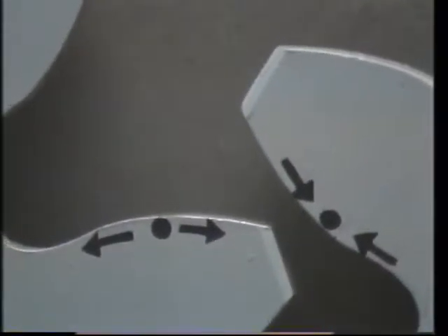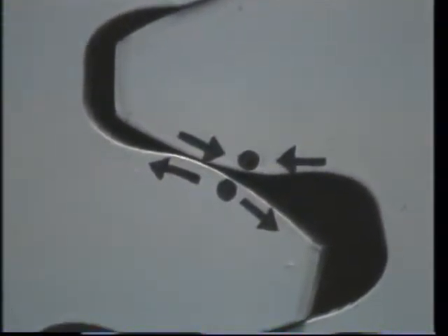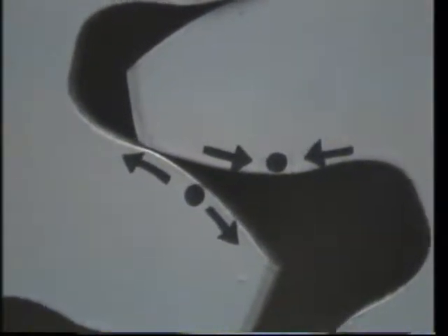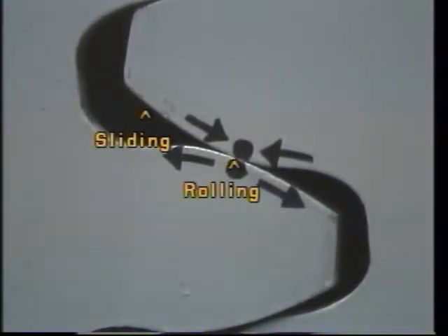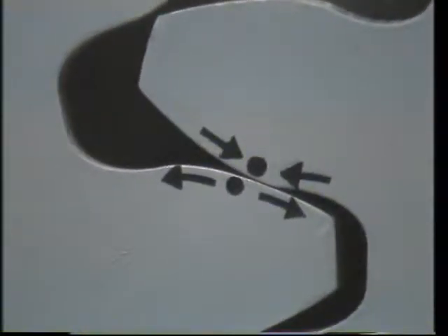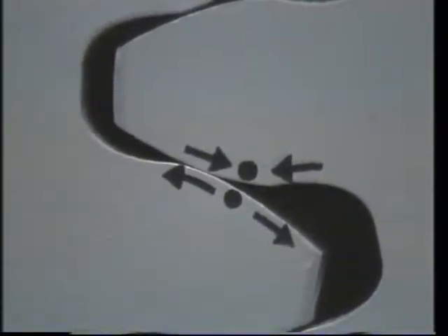The mating gear action is one of sliding and rolling. The sliding takes place along the tooth surface before and after the pitch point. But at the pitch point, there is zero sliding. Here, rolling takes place. Thus, at the pitch point, true contact is obtained between two mating gears. For effective sliding and rolling, the tooth form plays an important role.